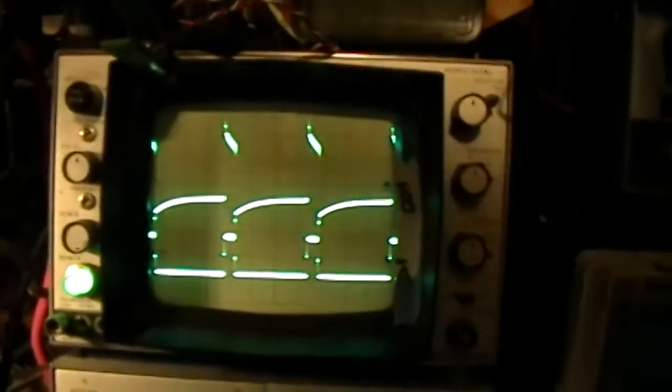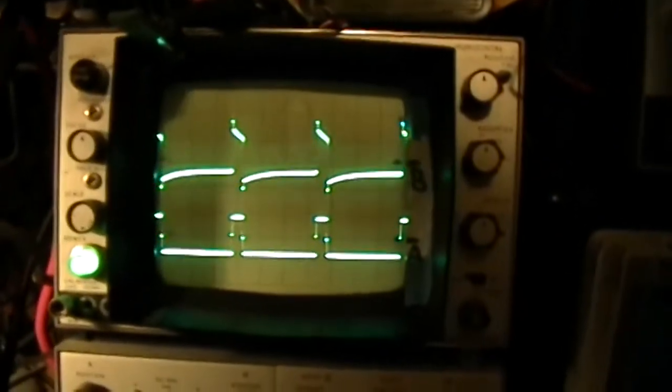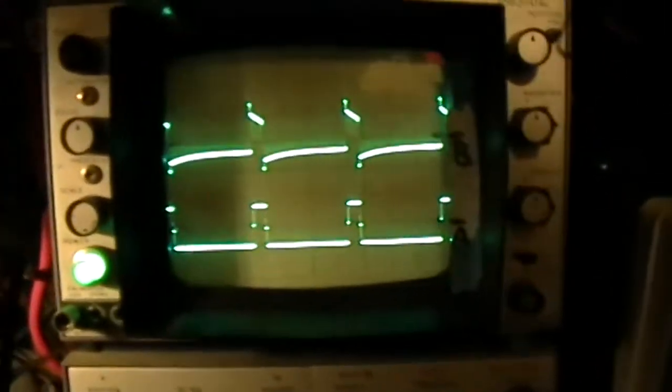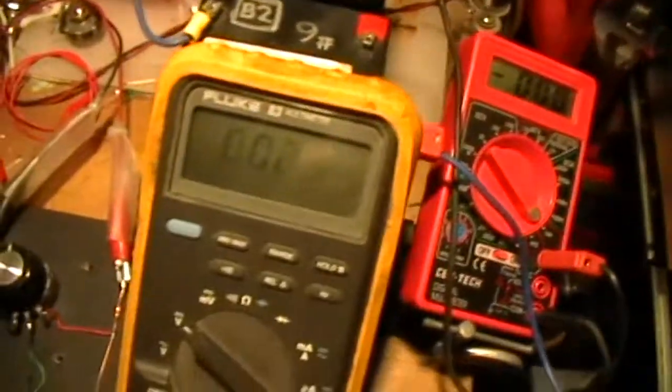But look what happens to the current through the current viewing resistor. I get a lot of current through that current viewing resistor without any battery supply hooked up. This is coming from the function generator, people. The function generator is acting as a power source and contributing to the current through the system. Okay, and I'm going to turn this back down. And we'll apply some power here.